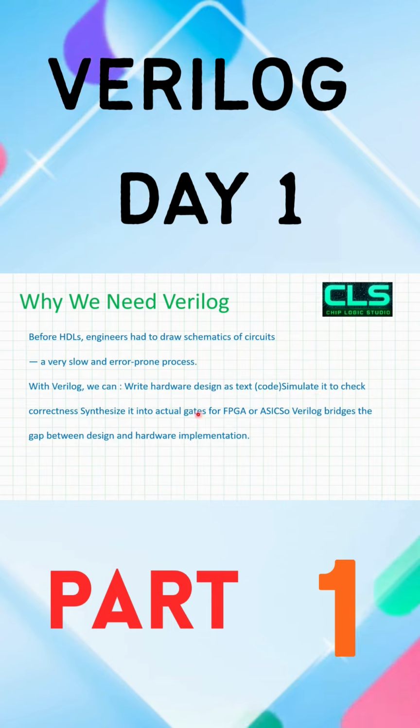into actual gates. An FPGA, for example, is different. An FPGA has switches inside that connect multiple gates, and you write the language, and the switches connect the gates to give you a proper circuit. That is a little bit of an FPGA introduction. We write code, and as per that the switches connect a circuit. For example, NMOS and PMOS connect to create a CMOS, which we can use as an inverter.